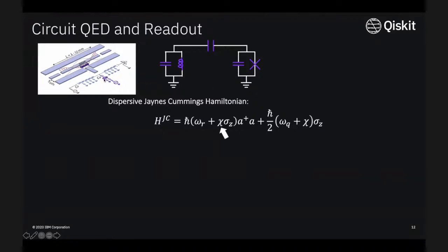What you'll sort of notice is that here this transmon in this diagram has two Josephson junctions. This gets into some details about how you can engineer transmon qubits themselves. And I'll also just quickly state that you can engineer a wide variety of different superconducting qubits. I'm just focusing on these fixed frequency transmon qubits that have a single Josephson junction. This is the one that we use at IBM. When you begin to change what sort of qubit you have, you'll end up changing the way in which you might decide to control the device as well.